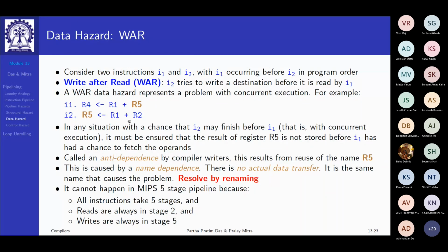That kind of constraint can be put in here, since I want a pipeline and the distance between these instructions is just 1, whereas I will at least need a distance of 2, so that the write back can be proper. So what we can simply do is rename this into something else. Of course, this will mean that we need more registers. So we can rename this and solve the problem.